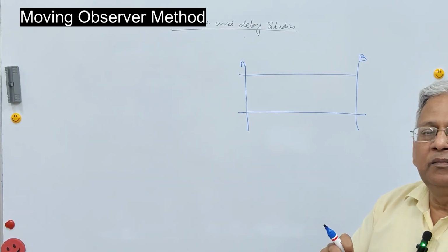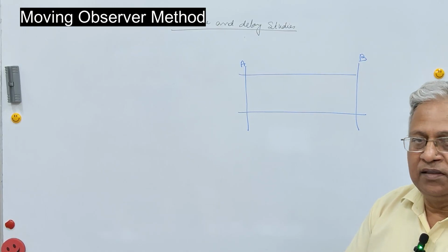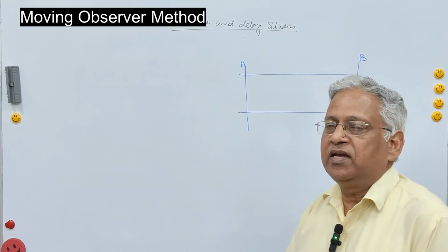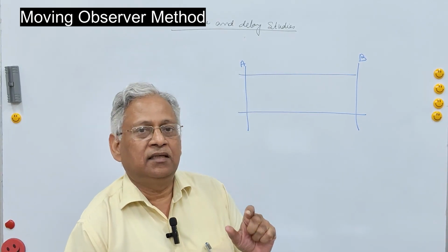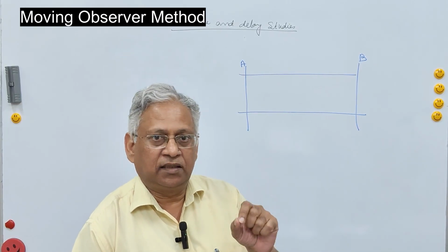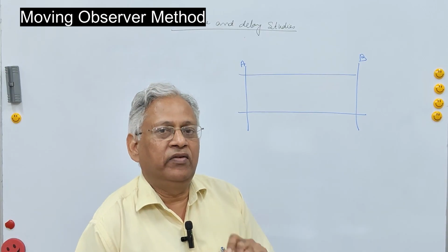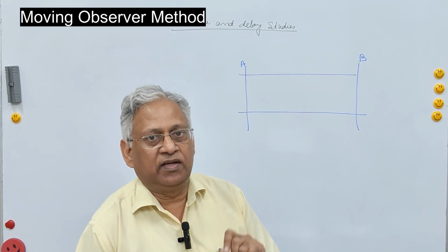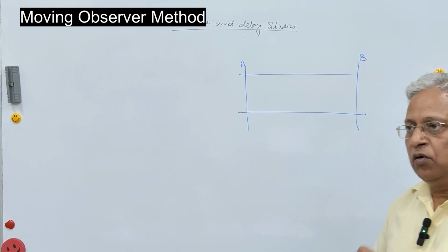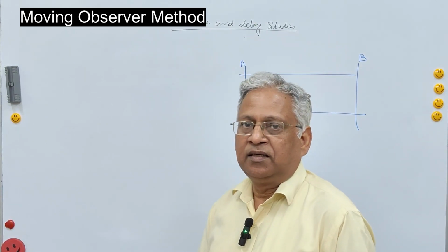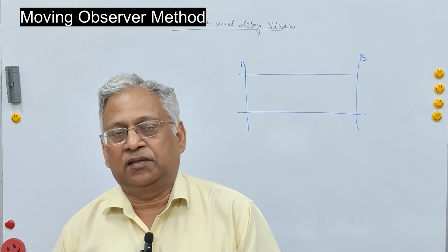The third person sitting with the driver will note down the number of vehicles which are passed by the test vehicle, means the number of vehicles overtaken by the test vehicle, and the number of vehicles which overtake the test vehicle. And the last observer will note down the number of vehicles coming from the opposite direction.